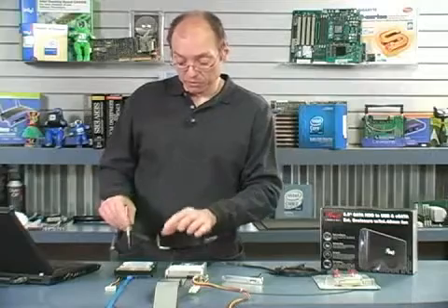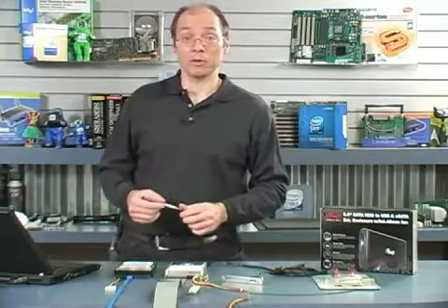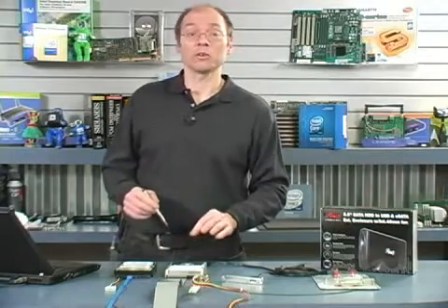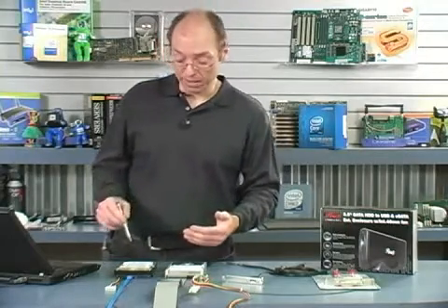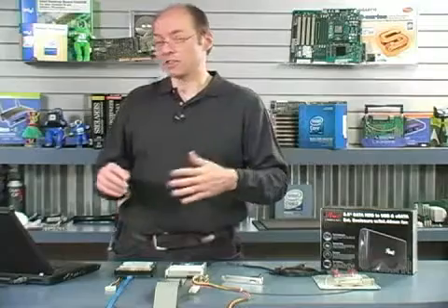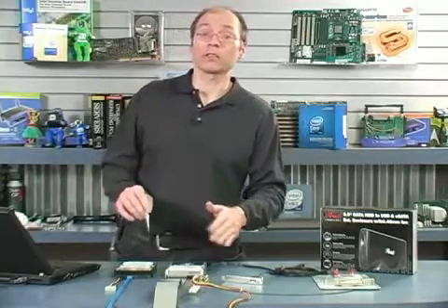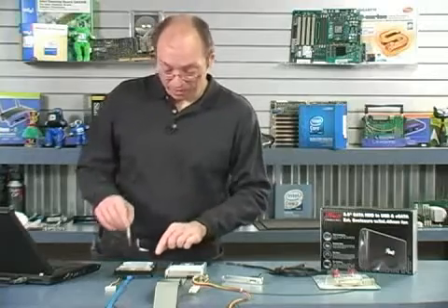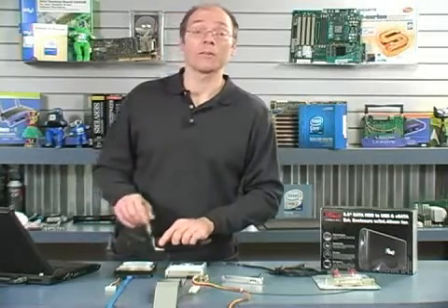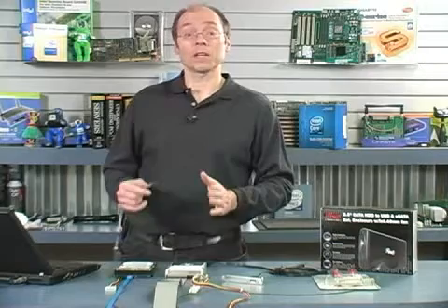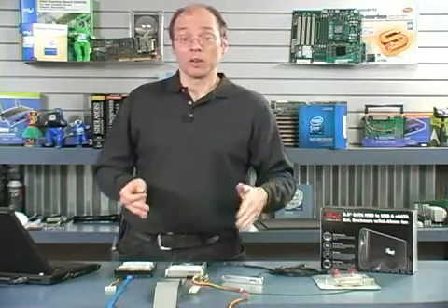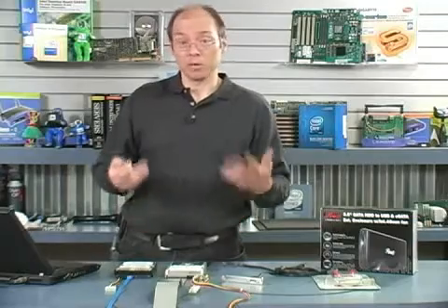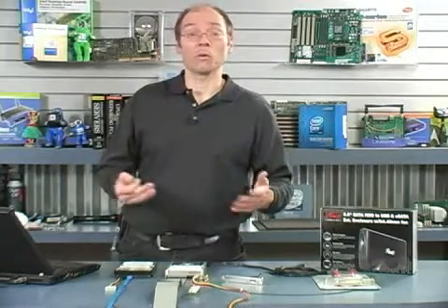You see, there are two variations of serial ATA drives available. Those that did the original 1.5 gigabit per second speed, and those that do the newer 3 gigabit per second speed. Sometimes those are called SATA 2 drives, which is actually inappropriate terminology. They are technically SATA 3 gigabit per second drives. This is a 3 gigabit per second drive. However, what was discovered was that sometimes if you had an older motherboard that had a 1.5 gigabit connection and you plugged a 3 gigabit drive into it, they wouldn't talk. The drive would not be seen or it wouldn't work properly.